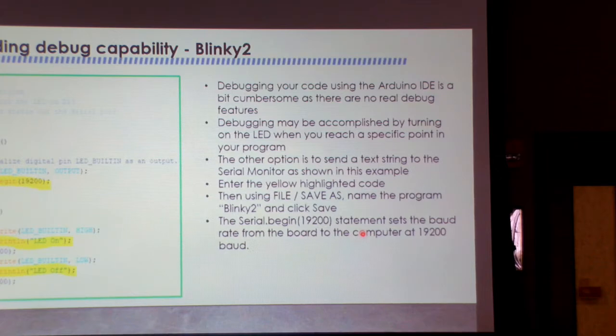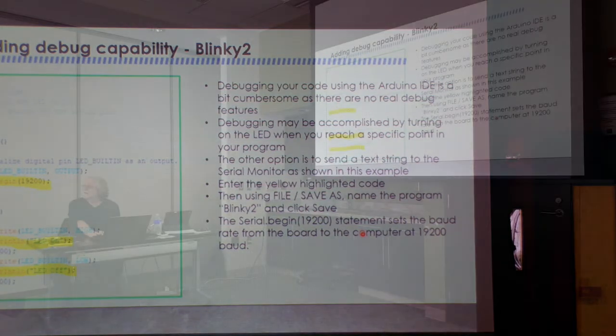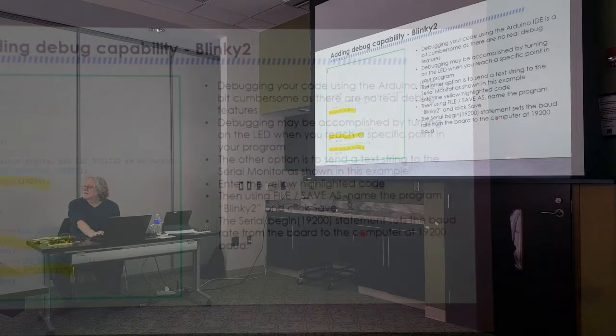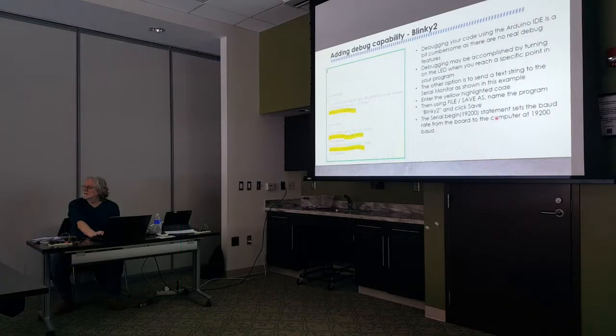It looks like the delay is pretty accurate, plus minus a few microseconds. There's a delay microseconds, which starts to get fairly accurate above 3 microseconds. Oh, so you cannot do 1 or 2. It will do something, a short delay, but you don't know exactly how long it is. So the delay should be fairly accurate, based on how accurate the 16 megahertz clock is. Right. Yeah. Cool, I didn't know that, thank you.